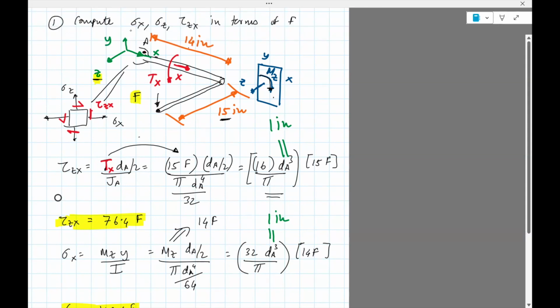Remember, there are only 4 things we studied: torsion, bending, shear, and uniaxial stress. Clearly, F is not going to be uniaxial. What about shear stress? Do you think there'll be a shear stress at A due to F? Okay, why not? So this is clearly not in the direction of this plane element. So there's nothing to worry about.